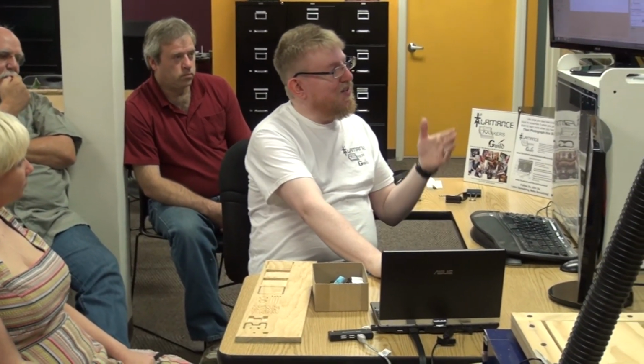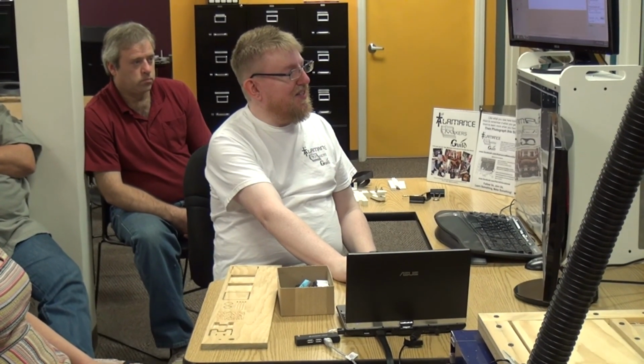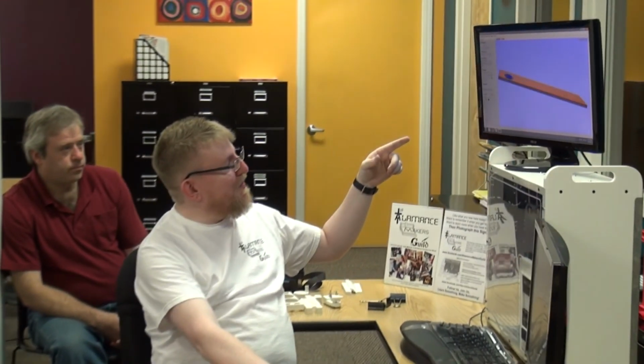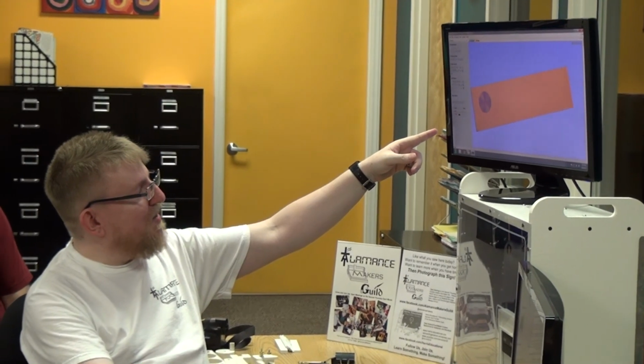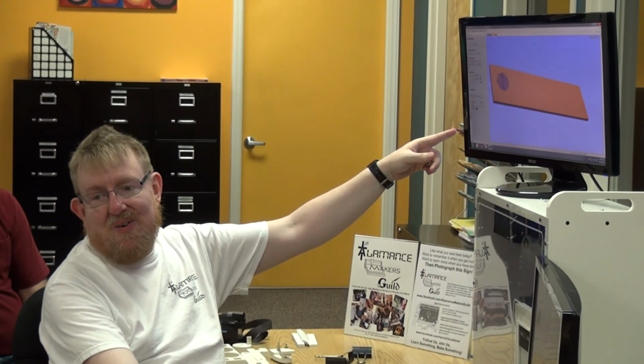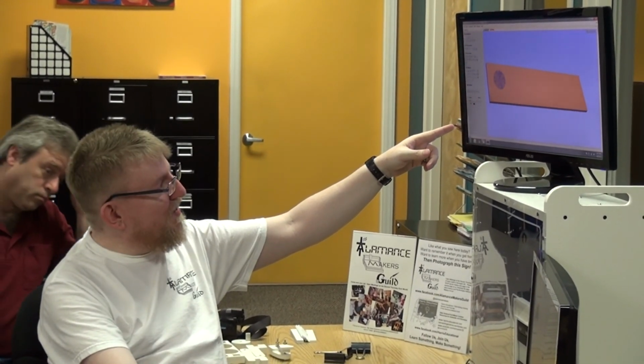And then how you're going to ramp in and out of the material, and you can give it a name, and you can tell it to select the vectors manually. There's just one. Oh, whoops. I have a vector selector. All right, so now it switches me to my three-dimensional view. So here's my piece of wood, and this blue circle, all these spirals show you where the router is going to go. So that shows you the toolpath that you've created.